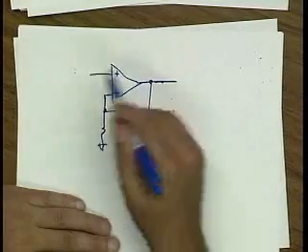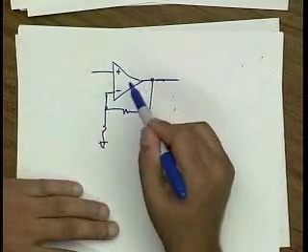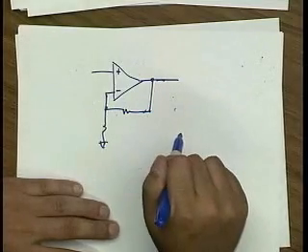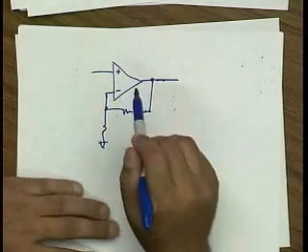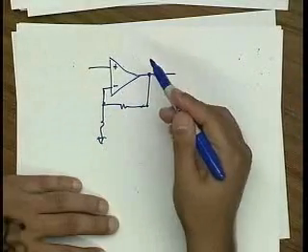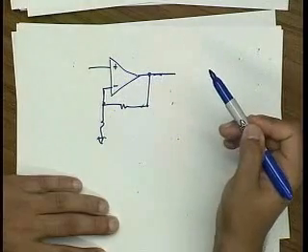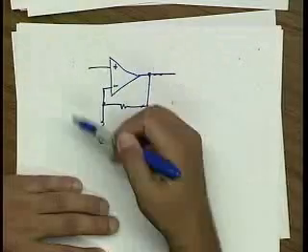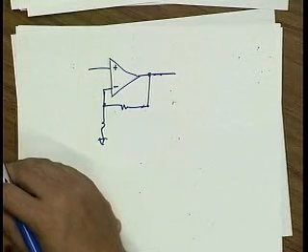Another way to look at it is the feedback system is correcting for the nonlinearity produced by the amplifier, because the feedback system only works with the fundamental. It's comparing the output fundamental with the input fundamental. And any difference is getting rejected. Now that difference could be due to the finite gain of the amplifier, or it could be due to nonlinearity. So the nonlinearity terms look like extra error terms that the feedback system is trying to get rid of. So that's a little bit of intuition on what's going on.